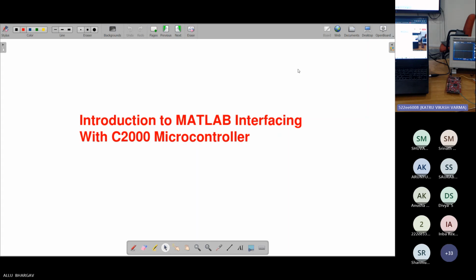We can provide some offset, and then only we can give it to the microcontroller. Otherwise, if you give a bipolar signal, the microcontroller will be damaged. If you provide offset or signal conditioning, then we can utilize either condition.